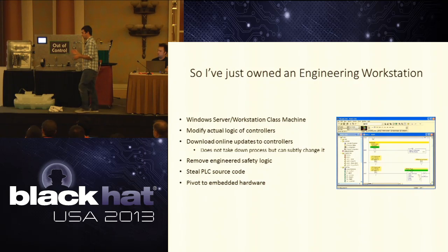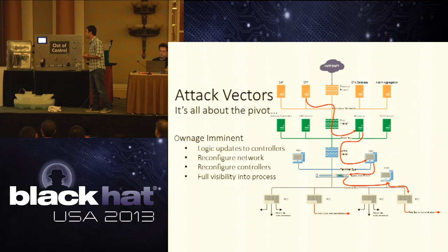but the language that you write on these PLCs is not C or anything like that. It has a couple of different forms, but primarily what you'll see is what is called ladder logic. And you can see obviously why it's called that, but it's essentially an old programming language that's relay logic. So it's meant for electrical engineers, not so much programmers. But if you're on an engineering workstation, you can actually steal the source from the controllers themselves. So you can actually get the logic files and modify the logic files on the PLCs while they're